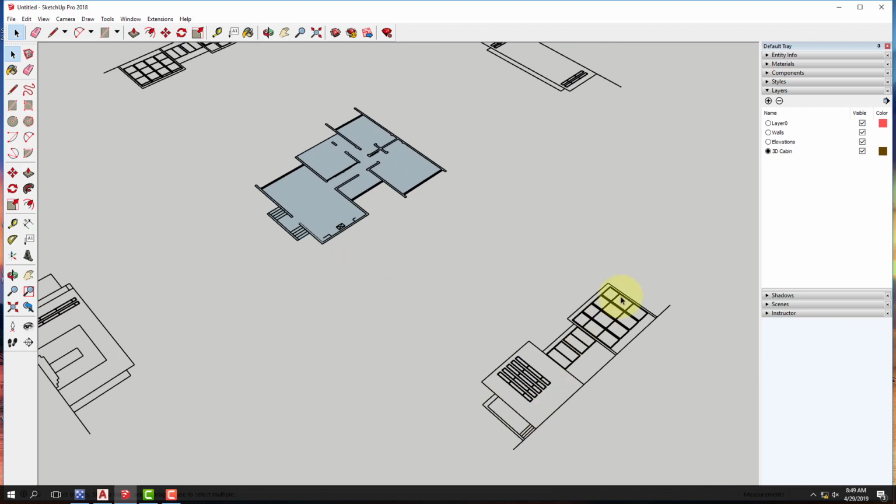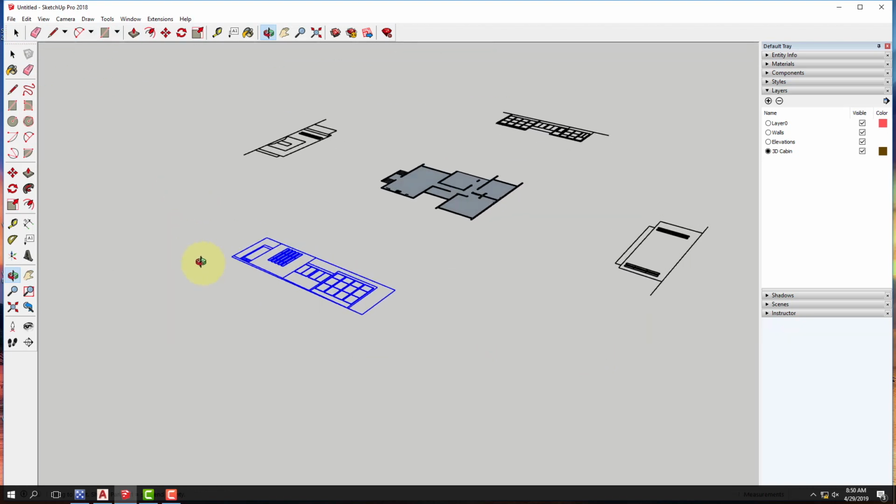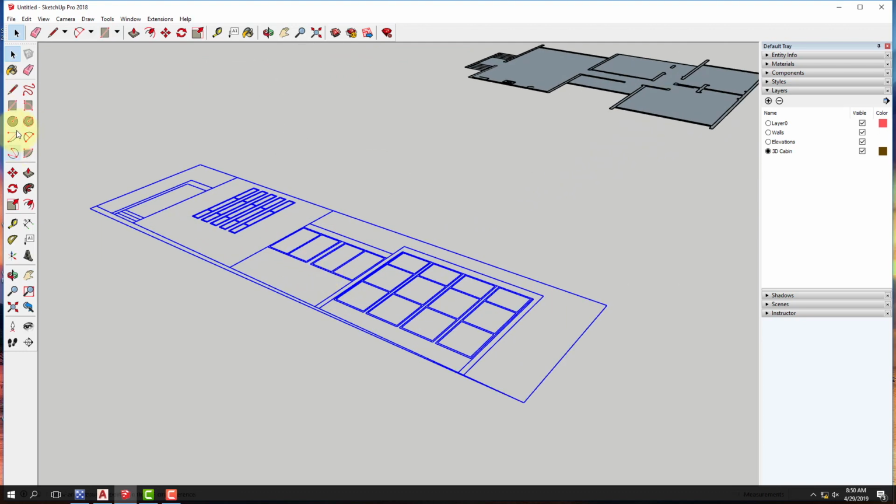Now, I already have the elevations drawn for how tall I think the building needs to be. So in that scenario, I can use these elevations to my advantage. So for right now, I want to rotate this component so that it's standing up vertically. And I'm going to do that by using a little cheater block, because if I went straight to the rotate tool, I'm only going to be able to rotate it in the flat plane. I want to be able to stand it up vertically. And SketchUp doesn't like to do that without some kind of a little three-dimensional object.